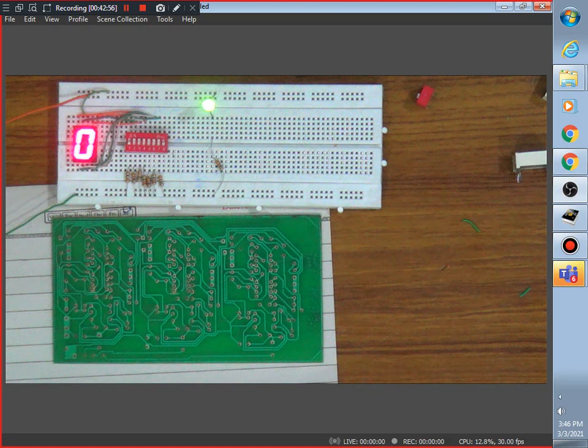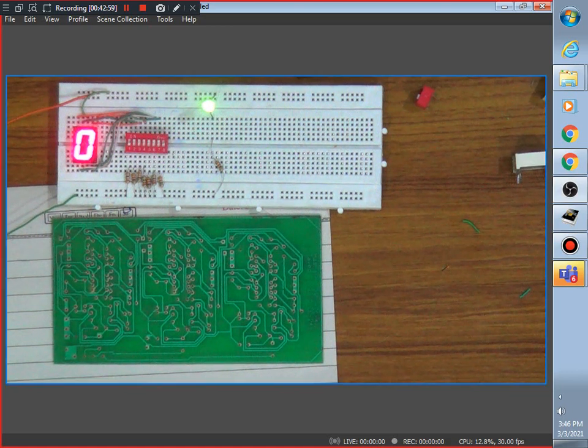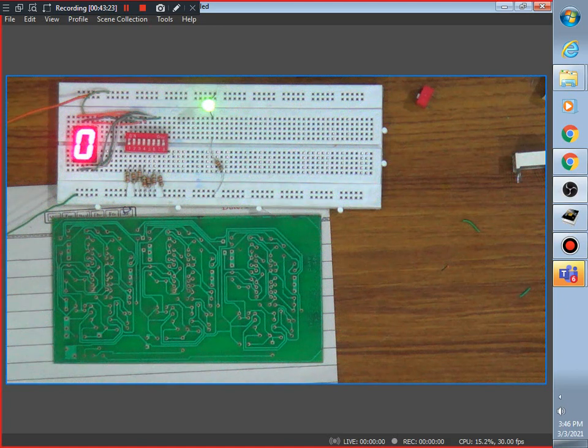Now since you are just beginners in this one, the tracks are going to be made in such a way that they have to be having some minimum width. Now what is that minimum width for you at present, since it is going to still have 10 milliamperes or 20 milliamperes of current over there. So I am going to ask you to have a minimum width of this track equal to 0.8 or 0.7 mm. Now practically your motherboards, your mobiles or something, they have the track width equal to 0.1 or 0.2 mm also. But practically this will be very difficult to actually make that PCB in the lab or anywhere.